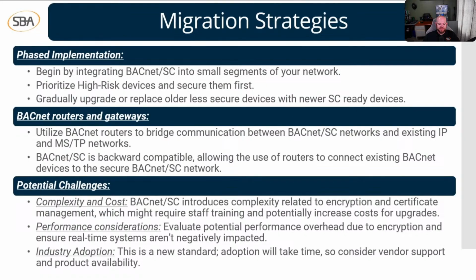We would evaluate potential performance overhead due to the encryptions that we've added, and then ensure the real-time systems aren't negatively impacted by any of this either. And then the third thing here is widespread industry adoption. So this is a new standard. Adoption is going to take time. And so make sure that you're considering vendor support and product availability when you're talking about upgrading to BACnet SC as well, because it may be a little bit harder at first than you think it is.